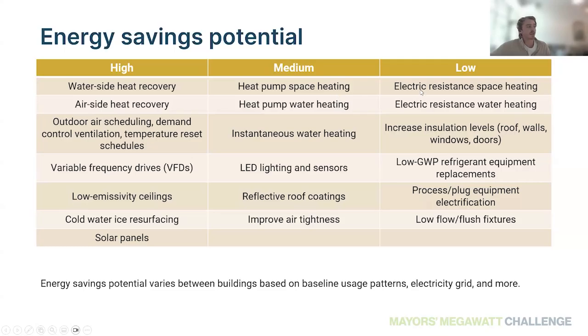Heat pump space and water heating, relative to pure electric. By going from fossil fuels to electric, you're getting some inherent savings from increased burner efficiencies, but that's primarily an emissions reduction measure. Heat pump technology is just more efficient than resistance.